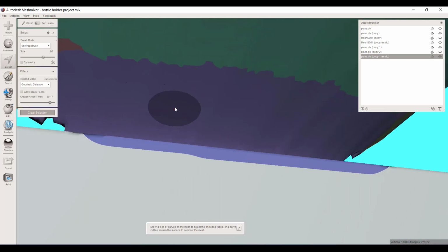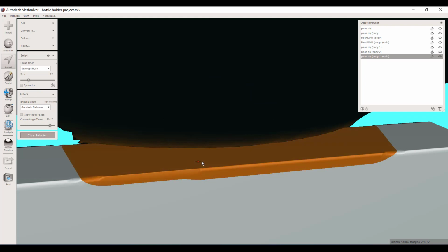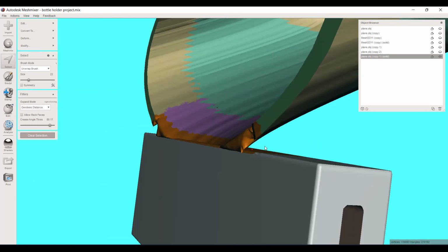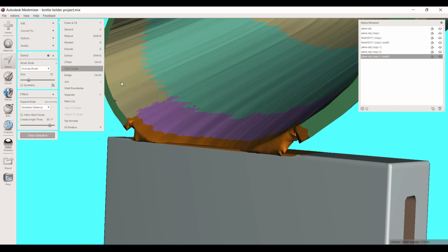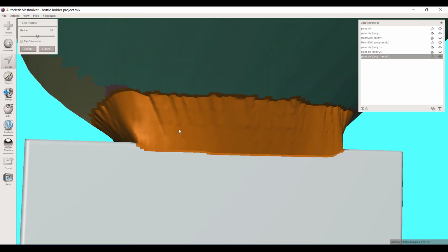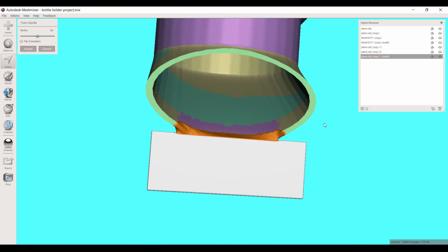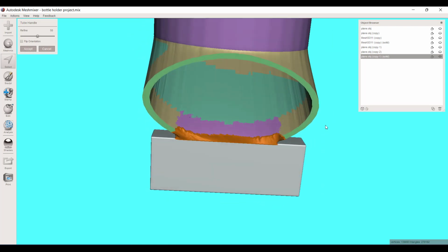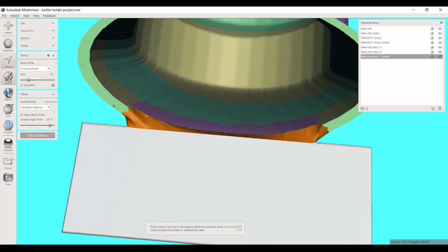So what would happen if I selected all of this group and all of that group? And let's just try this. I don't know for sure if it'll work, but let's go to Edit, Tube Handle. Now I don't know why they call this tube handle because it's kind of a goofy description of it. But that more or less accomplished what I was after. I don't love this little rough edge here, but again, how picky are we trying to be here?